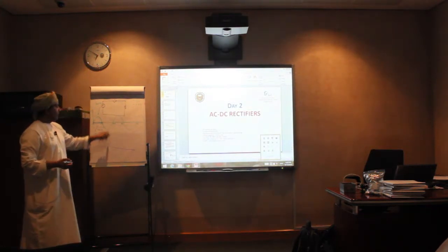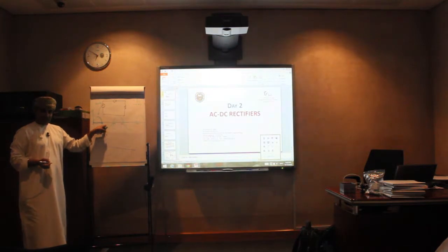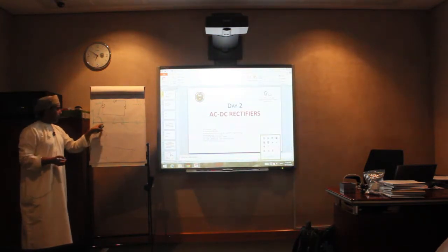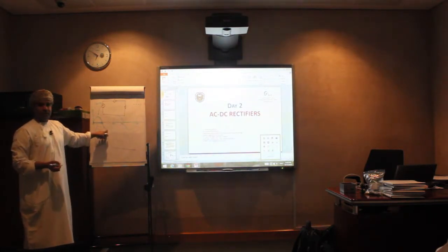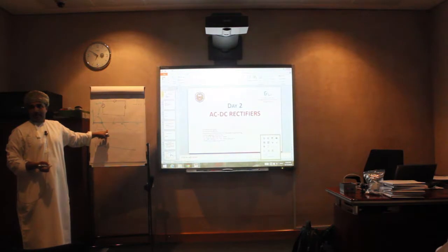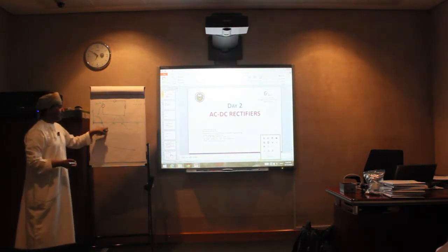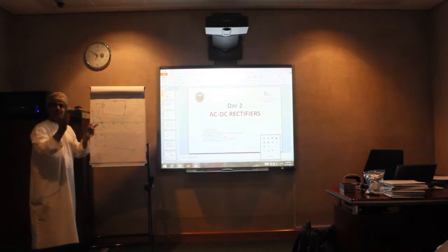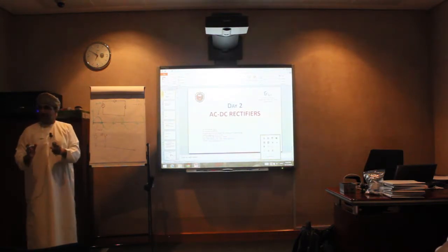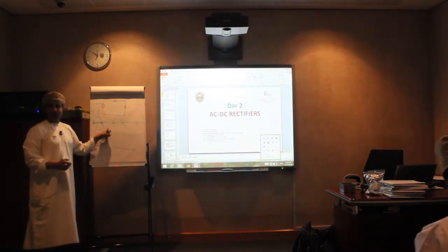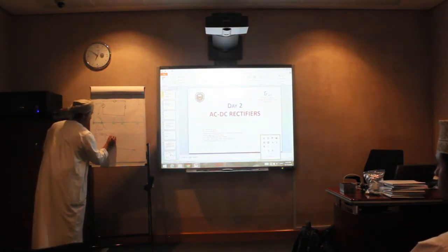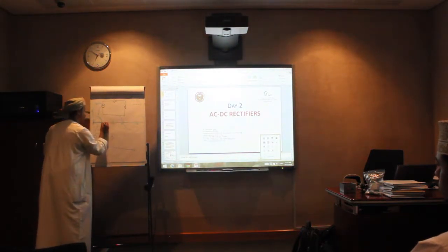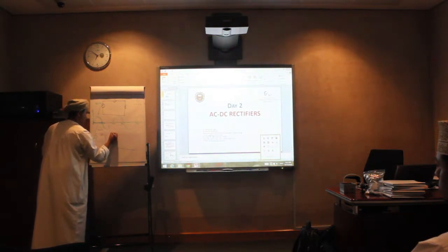And after that, in the second half cycle, from pi to 2 pi, is the source negative or positive? Negative. So when it is negative, that means it is located in the second region, which is reverse biased. Therefore, it will not conduct. So that means in this case, I will have the circuit like so. This is negative and this is positive from here to here, and this circuit here.